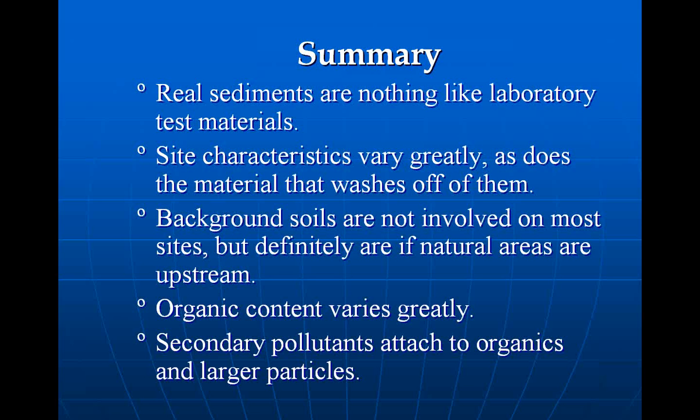You've seen them on the strip at the top. You can observe that the Silica Sil 106 is probably more like what you're likely to encounter in the field than the OK 110. You didn't see very many perfectly round, highly rounded silica particles. We know for a fact that the density of field materials is about 1.7 times as heavy as water, and the density of silica is 5 times the density of water. We know that the angularity of the particles has a seriously high effect on the settling rates, as rounded is easier as opposed to angular being tougher.